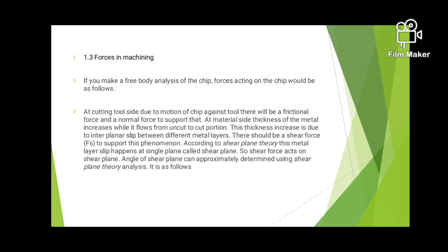Forces in machining. If you make a free body analysis of the chip, the forces acting on the chip would be as follows. On the cutting tool side, due to the motion of the chip against the tool, there will be a frictional force and a normal force. On the material side, the thickness of the metal increases while it flows from the uncut position.